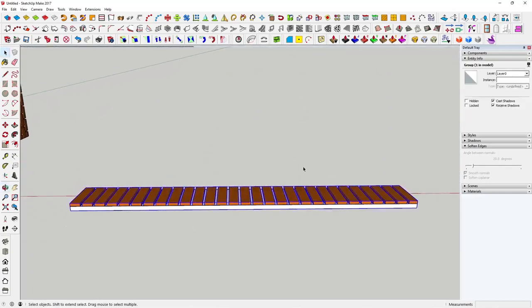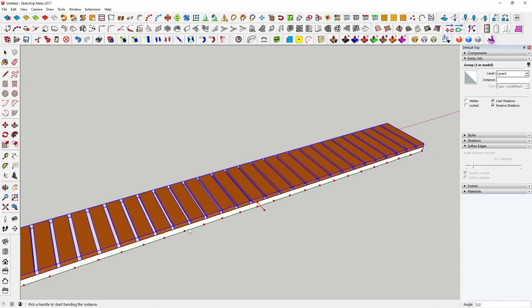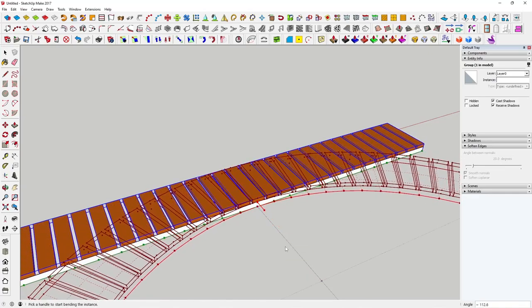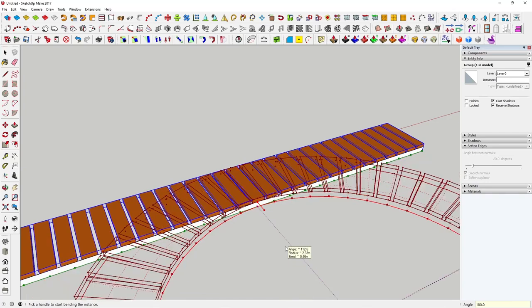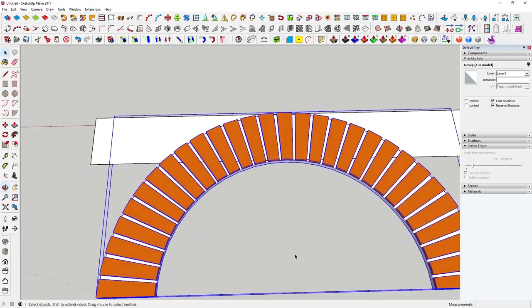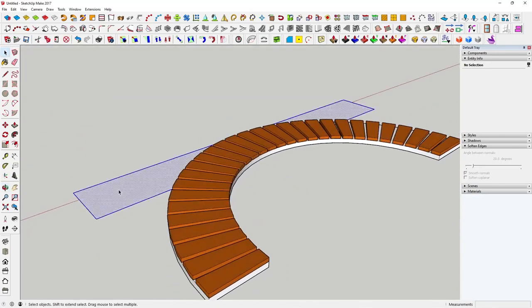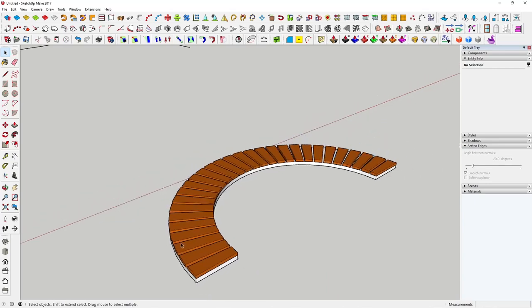We'll get our bricks. We'll use our TrueBend. We've got the same again. If you see we've got the segments, it's going to bend it along there, and this is our, well, I suppose our bending tongs. Anyway, click on and we'll start pulling. We'll put in the angle as 180, enter, and I'm happy with that. We'll press enter again, and then we've got a row of soldier bricks. Get rid of the excess geometry.